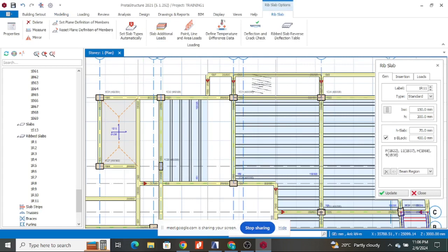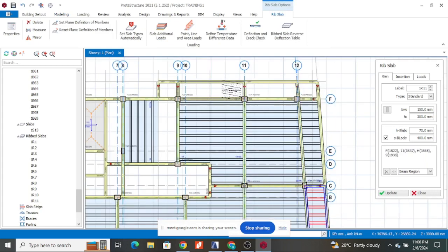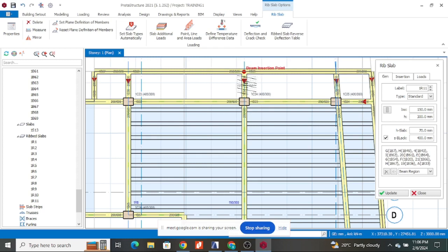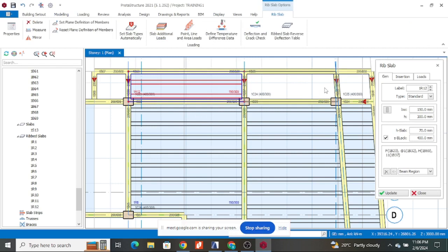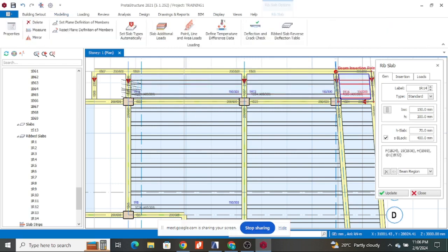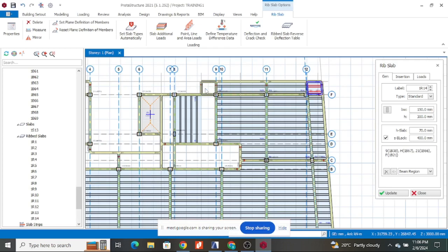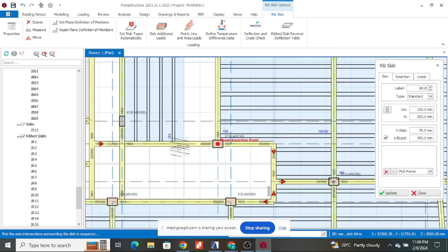Also, there are a few things you need to consider at this cantilever. You realize that now I'm not going to have my cantilever from the slab. I'm going to have my beams acting as cantilevers. Therefore, they are the ones that will carry the ribs. And if I start tying the ribs in the other direction, it means they are going to load this external beam, which I don't want. So I'm still going to tie them in the direction that the others are running.